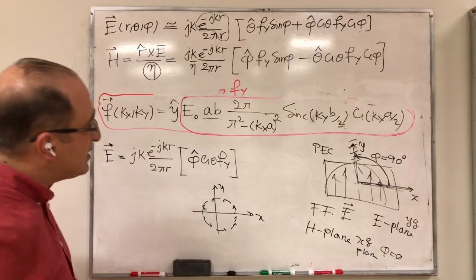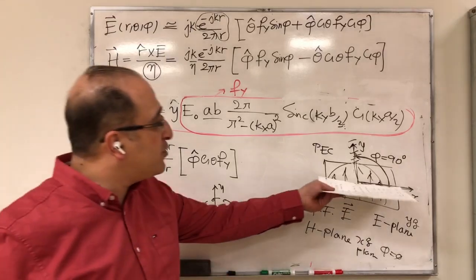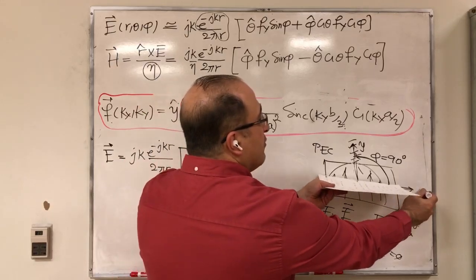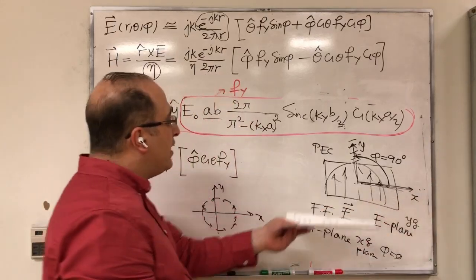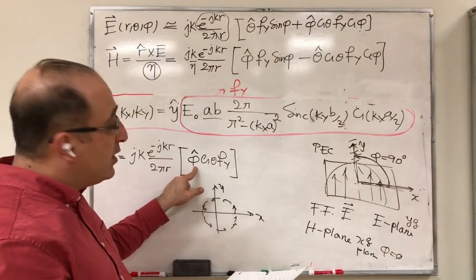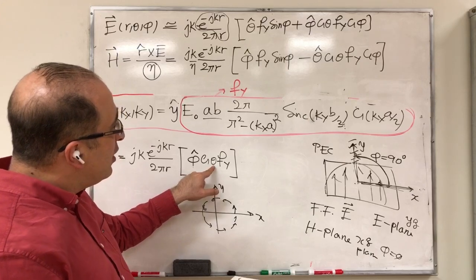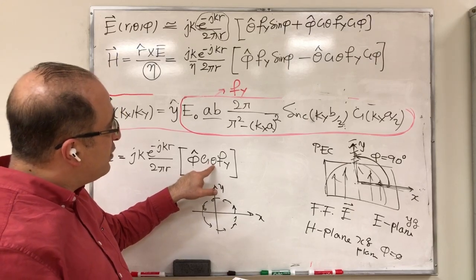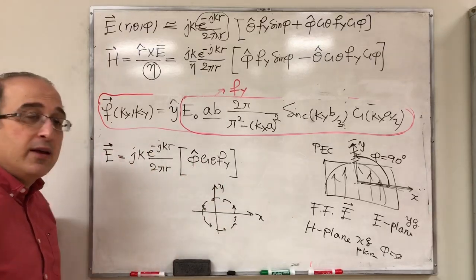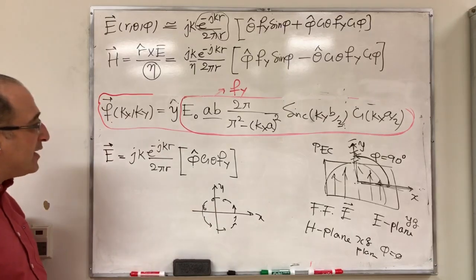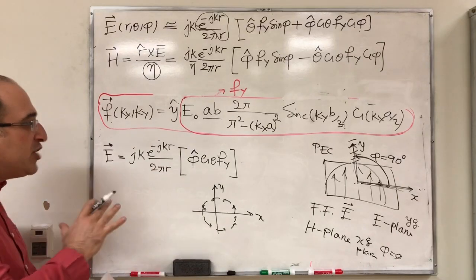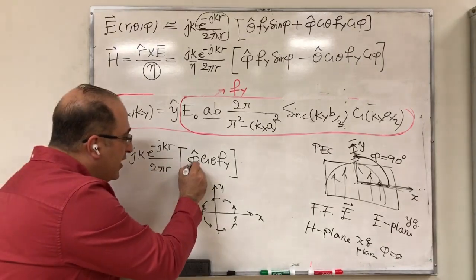And we immediately see that it is, because if you are on the H plane, this is your expression. And if you further say, I want to check what's happening very far on the x-axis, then you are on the PEC, and you have a phi hat component, tangential to the XY plane. But then immediately you see that if you are on the XY plane, theta is 90, so cos of 90 is 0. So the tangential component vanishes, and that confirms it is correct. This is a bit of detail, but I think it's still good to check these types of things after calculation.